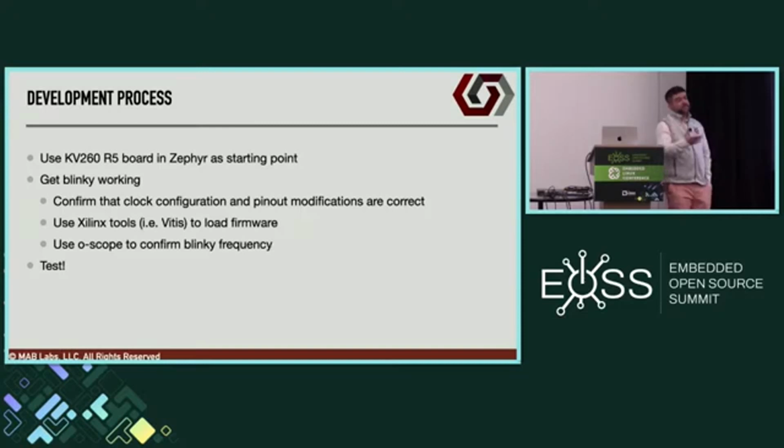The next step is just to get UART working. So if you have Hello World, that's higher confidence that your clock configurations are working, because UART is a little bit more sensitive to clock configurations, et cetera. So if your clock is off, you might be getting just garbled data that's coming out of your UART.